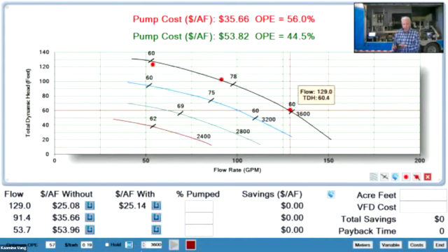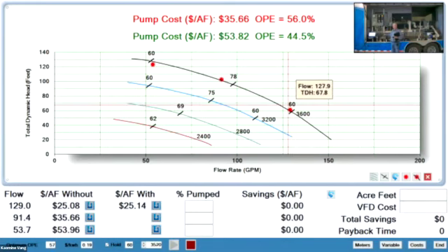So I go down to the bottom here, and I highlighted the thing that said 80 right now. I'm going to plug 60 feet of head in there, not 60 pounds pressure, sorry, 60 feet of head. That's about 26 pounds pressure. That's going to be our number that we stay on. All right. And then I'm going to click this hold button right here. And then I'm going to go back to my valve, and I'm going to match up that flow rate with the other condition.